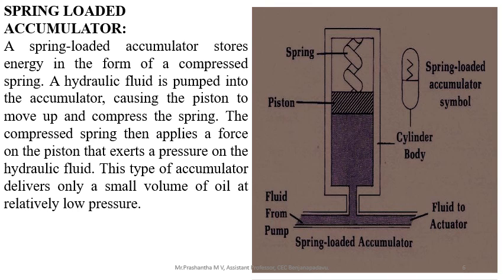It also has some limitations. Mainly, the pressure exerted on the fluid is not constant. They deliver a small volume at low pressures. These are a few of the disadvantages of spring loaded accumulators.